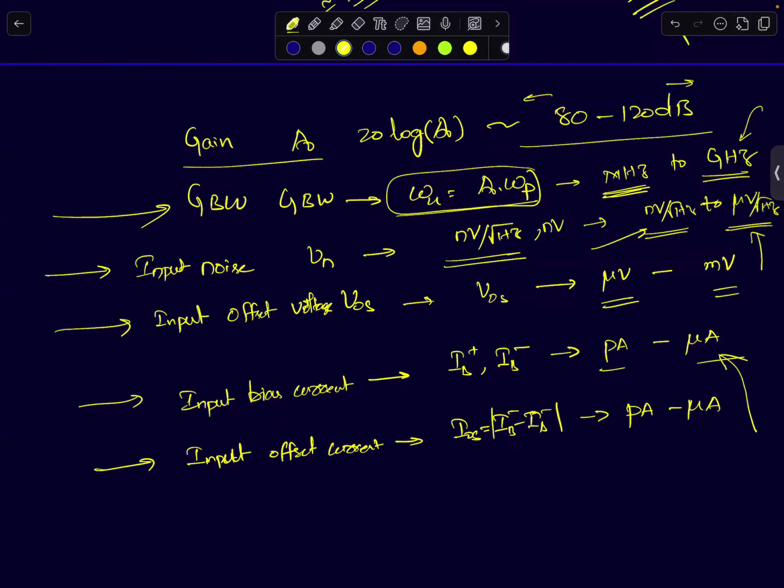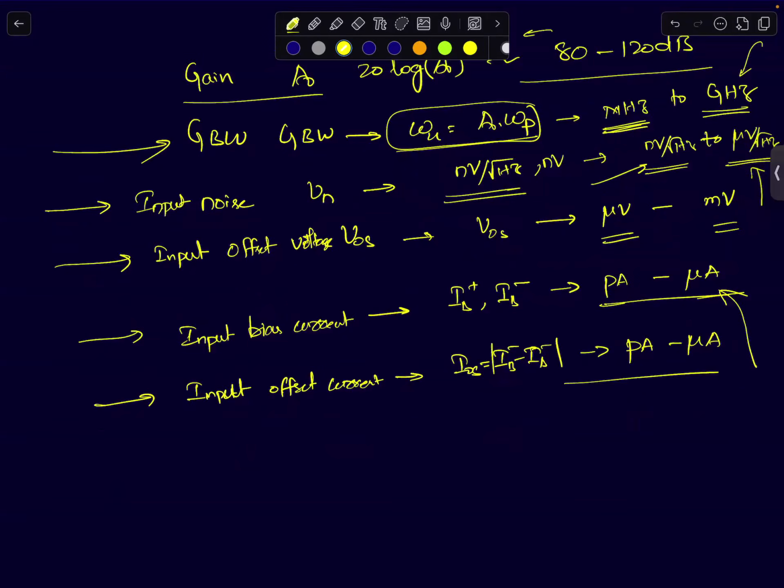There are some techniques using which we can reduce the input bias currents, so those op-amps will be priced higher. Your μA741, again we'll look at the data sheet later. It will be in the order of hundreds of nanoamperes. Offset current can also be in a similar range of hundreds of nanoamperes. Pico to microamperes. And usually it will be picoamperes for field effect transistors, JFET, MOSFET-based op-amps and all that.